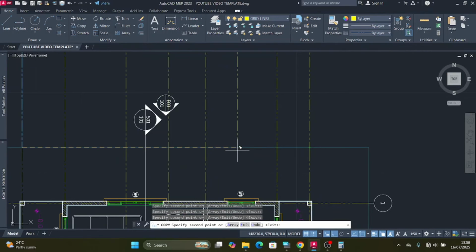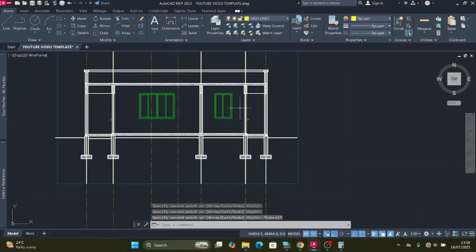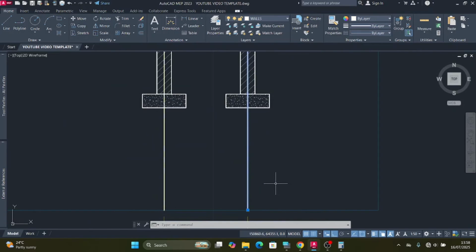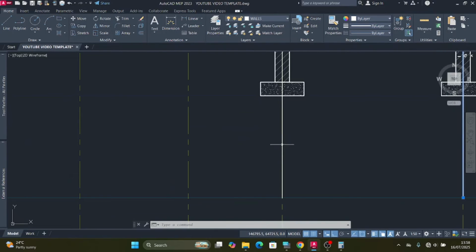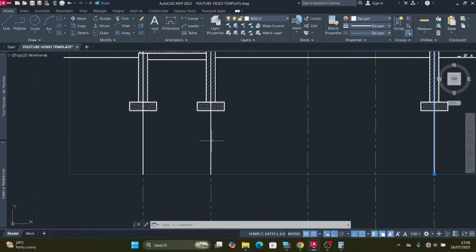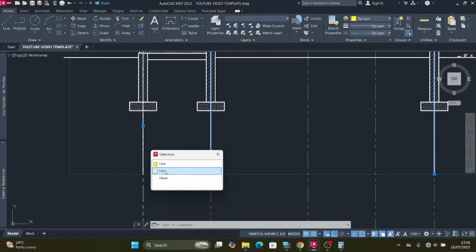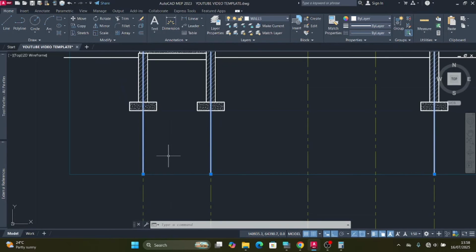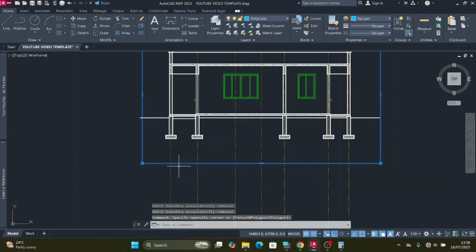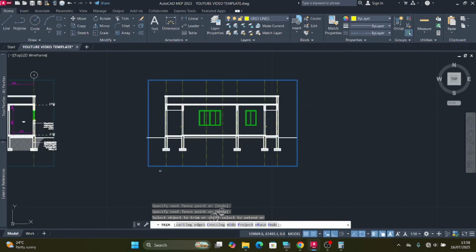All right, press escape. Then next, I'll click at the overlap, then select line, then do the same thing here. Then I'll press delete at the keyboard. I'll select this outer rectangle, click at the trim command, then I'll trim off these other lines that are protruding out of the rectangle. Press escape.